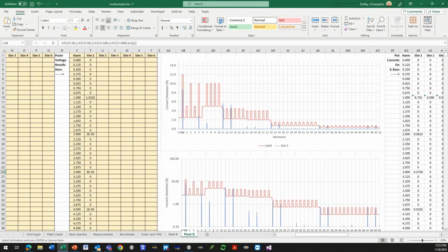But to model those, solar banks, which include a source inverter, you need to request from the manufacturer a Norton model. Because they're going to be source inverters most likely, you would want to have the Norton model that has both the harmonic current magnitude and angle, along with R and X at each one of the harmonics, as shown.